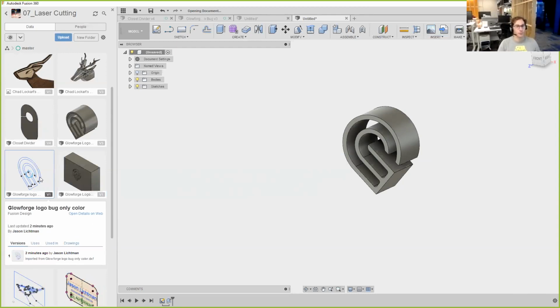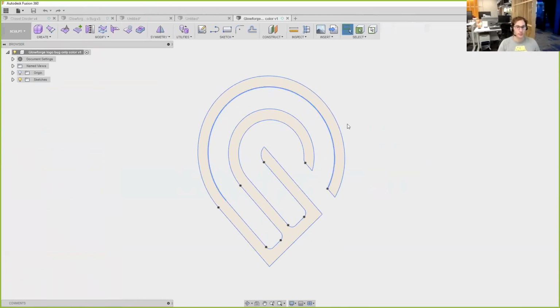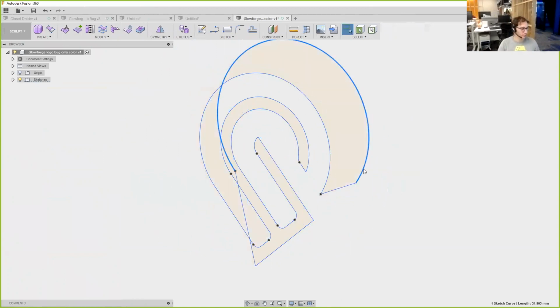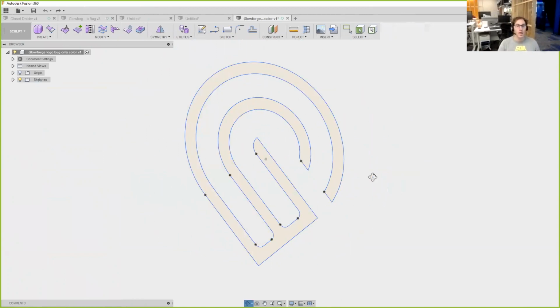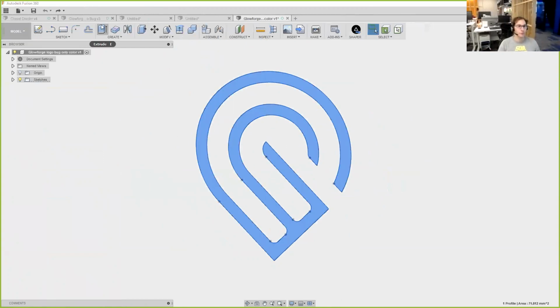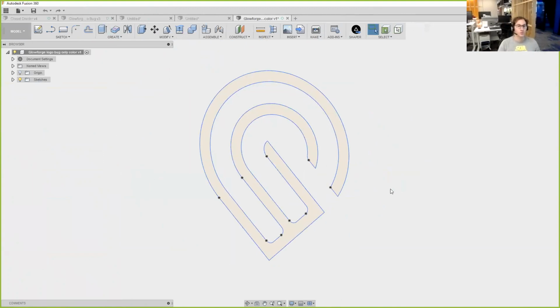This time it is going to open in Fusion 360 itself, and it is coming with entire sketch entities that I can select, and everything is looking really good. This is exactly what I'd expect. I have all blue lines, which means I can still edit it, right? You can see here I'm moving things around I probably shouldn't have. So I'm going to undo there. And I'm seeing the yellow on the inside, which means that I could turn this into a 3D thing whenever I'm ready, right? Just like this. We did that earlier today. And it also means that I could use this, right? So overall, I would say that uploading a DXF is actually perfectly reasonable, right?